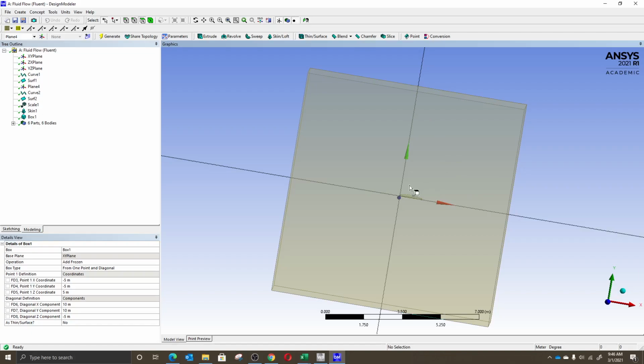We are mostly interested in the area surrounding the airfoil, so you can also create a smaller sphere that encloses this airfoil, and in the meshing part, make sure the mesh is finer here, with more data points inside this sphere.